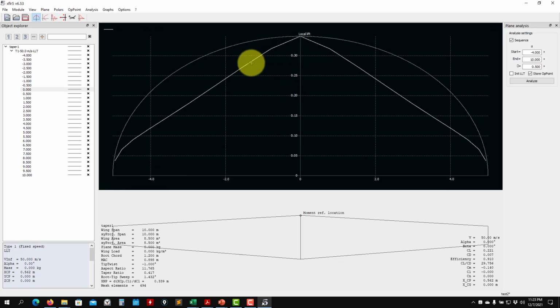So probably we added too much lift, or probably it would be better. So these are the steps. What I'm showing you, I think you should follow that also for your wing. The most critical thing, as you can guess, will be the airfoil selection. So probably we can add a section at 2 and probably one at 4, or remove the